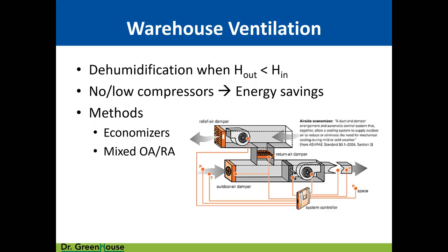But we really only want to do it, and this is the trick, when the humidity content, the humidity ratio of the air outside is less than inside. If we introduce outside air that is more humid than what we are controlling to inside, then we're actually going to increase the humidity content of the air inside, defeating ourselves.